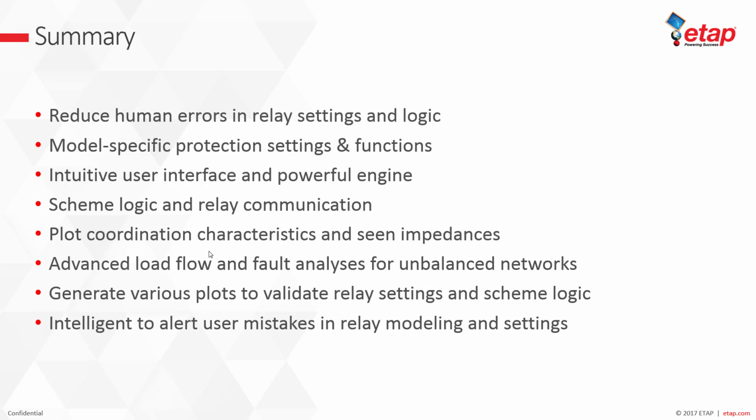So we are using a very accurate and advanced load flow and fault analysis that works for the unbalanced network. It supports series compensated and coupled lines. It supports HVDC, SVC, and all these complicated elements in the power system. This tool generates various plots to validate relay settings and scheme logic, especially the time distance resistance plot that we showed, which in one shot can tell you if the relay settings and the logics are properly set.